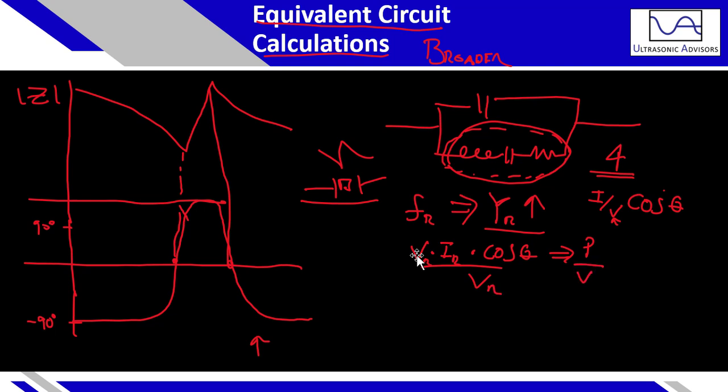So if you divide both of this by power, so voltage to power ratio, it ends up being the same thing as calculating the real admittance. So again, the real admittance is going to be what we're going to look for, and that signifies the resonant frequency. It's also related to power dissipation, which is a more readily understood concept, but not just power, but power per voltage, because the voltage for a test instrument, even an impedance analyzer, or if it's a high voltage amplifier, those do change as a result of the load, and they're not always predictable and linear.